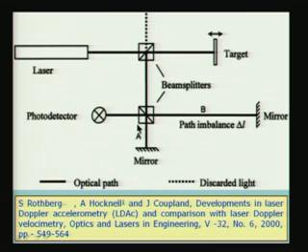Let me just briefly see what it consists of. In the next lecture, we will be able to look at things in more detail. So, we have a laser source, and then we have a beam splitter. Part of the beam is sacrificed, it goes away from the system, and part of it goes and hits the target. The target is the one which is going to be vibrating. So, we want to measure the amplitude, the velocity or the acceleration of the target, and this beam hits the target and is retro-reflected, and then the beam splitter will send part of it at 90 degrees to that. It will be incident on a second beam splitter and reflected, and it will fall on a mirror, and we have deliberately a long path which we call path imbalance delta L. In the next lecture, we will find out why we have this path imbalance.